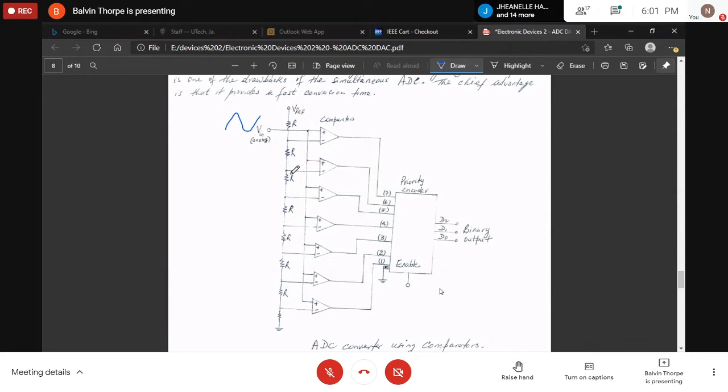And let's say the input signal, you're sampling the input signal each time, right? Yes, sir. And what it is doing is that every time the input signal that is coming in at each interval in time is going to be compared. But because of the rated value of the resistor, it's going to determine whether or not that reference voltage, based on the resistors, the voltage divider of the resistor, that voltage is going to be greater than or less than the reference voltage. And so they're going to put a 0 or a 1. You follow me?